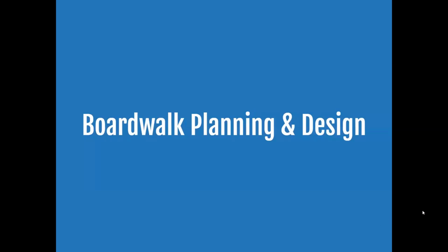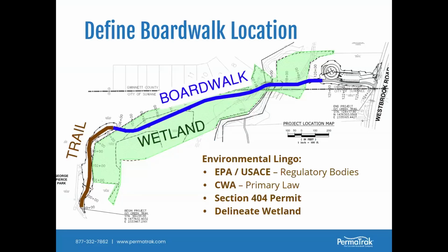I've got a lot of slides to show you, and John Dove is going to be advancing the slides for me. So it all starts with deciding, where do you need to put a boardwalk? And I'll say this, if you're a trail designer or a greenway planner, you know that one of the more expensive items on your trail greenway is the boardwalk. The boardwalk is a costly item, so you want to minimize the length of the boardwalk as best you can. Bridges and boardwalks are going to be the big cost items on trails. I've seen that over and over through many of the bid forms that we've looked at.